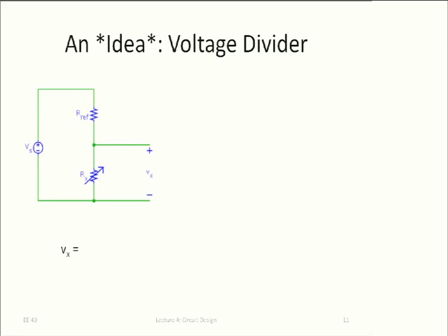So now we have that thing. We have that resistor here, the strain resistor, and this is our goal, right? We want to make a voltage, and how do we change that resistance into a voltage? Well, here is the first idea. What is this thing called? A voltage divider, exactly. So now, can you figure out an equation that relates Vx to Rx?